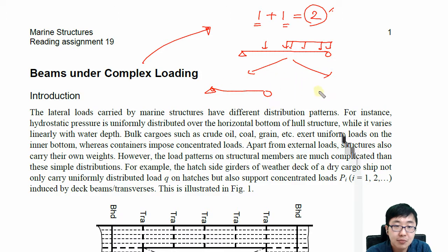This is one beam, exactly the same beam, and then we have P and Q. In this case we will consider P only, and here we will consider Q, and then we will add up everything like the moment functions, as well as the shear.